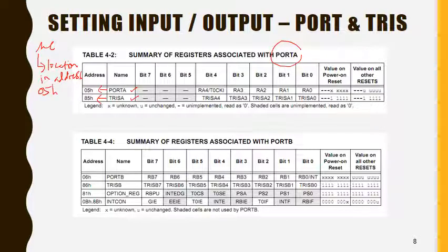So 05 here is the location or address of the register in the internal architecture of the microcontroller. The H over here means that the address is in hexadecimal form. If we convert this hexadecimal address into binary form, it equals the location 0000 0101. So this is in its binary.